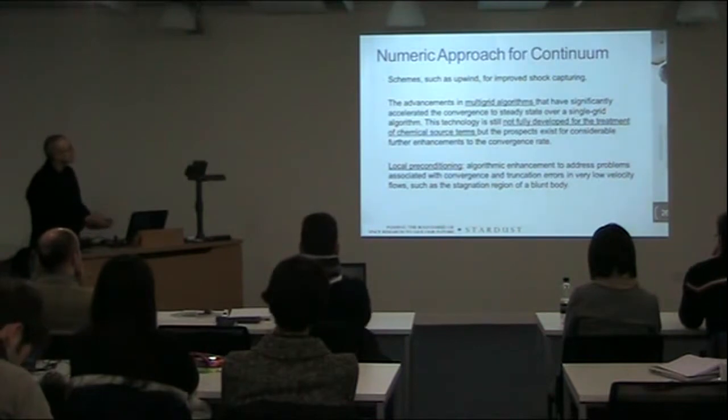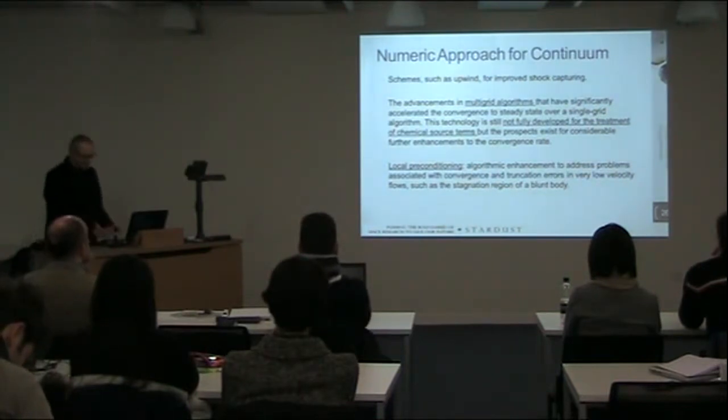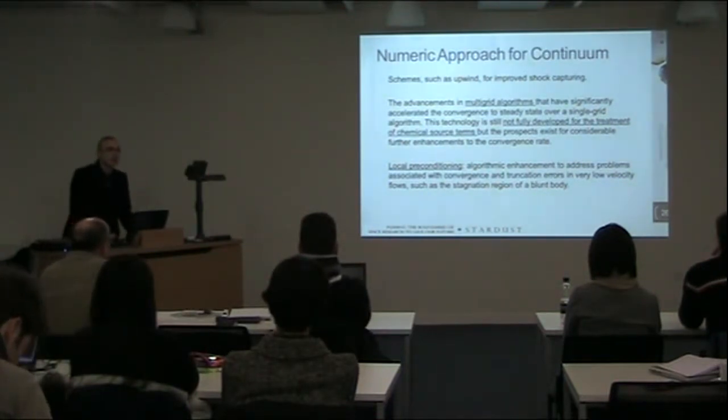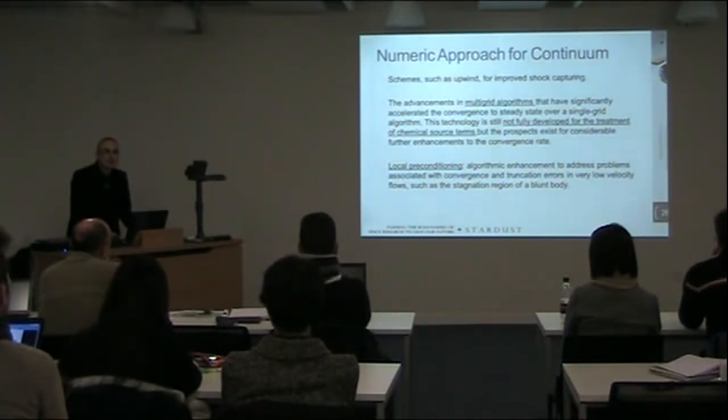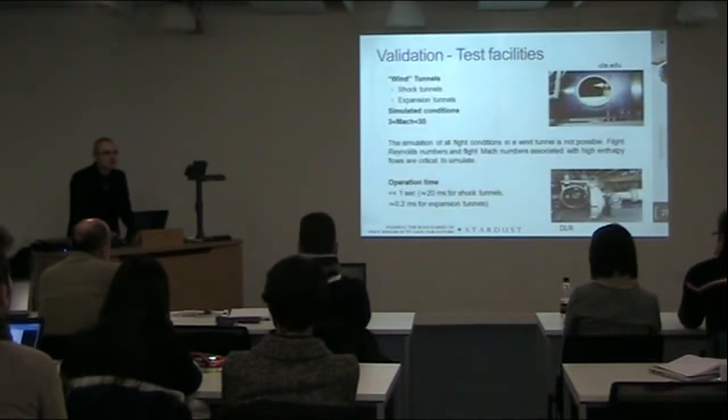And of course, what is really important for hypersonic flow is local preconditioning, which is a technique used when you have in the same computation points where the velocity is very small and points where it is very, very high, which is actually this case.